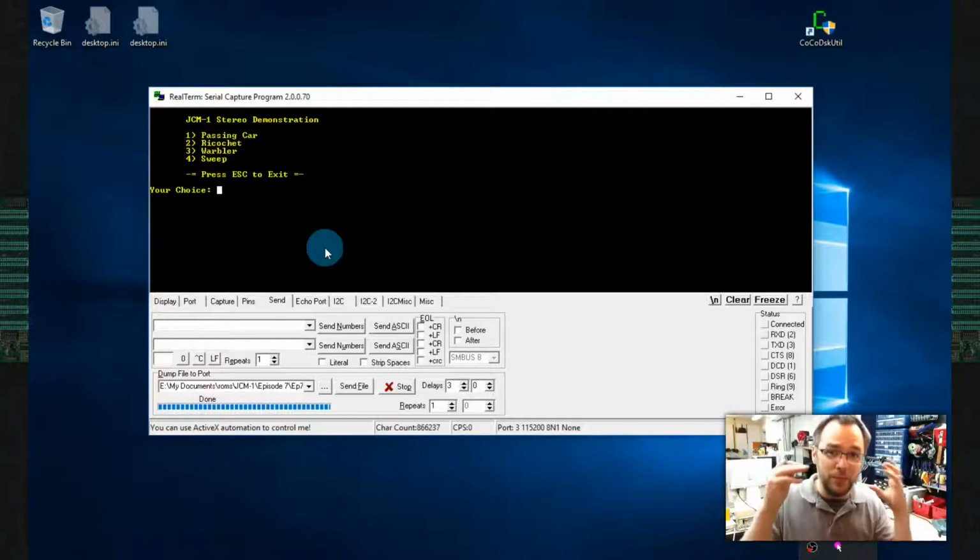So, the computer has basically a fully functional sound system. We've got 6 channels that can do independently or combined noise and tone with all the cool envelope features that the 8910 has. It's not as cool as a SID chip, but it's good enough for us. And then also now we have stereo panning, something that almost no computer from the 80s had, mainly because you didn't have digital potentiometers back then. But this is a little cheat that I wanted to put in just because I wanted to put it in, and it was easy enough to implement.